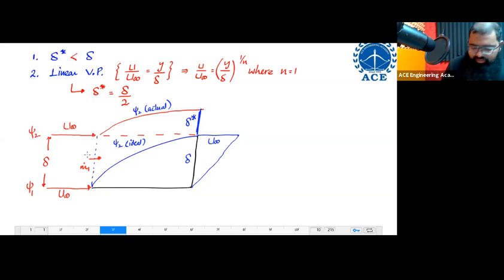So basically density into area means delta multiplied by width perpendicular to screen, capital B, multiplied by velocity u infinity. Now you see density, let us say, is constant. Width perpendicular to screen is, let us say, constant. So m dot 1 corresponds to delta multiplied by u infinity. So basically this rectangle over here is representing my m dot 1.